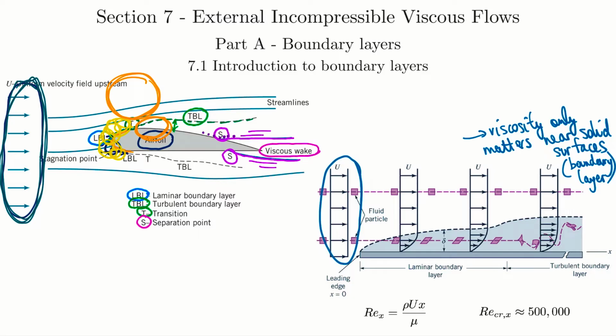Before you reach the flat plate, we have a nice even velocity profile. So out here we say U is constant, and we basically have steady, inviscid, incompressible flow. Because of those things, that means essentially P is constant as well. If velocity is not changing in those inviscid conditions, then we don't have a change in pressure either. So out there in the inviscid space, we can calculate those flows, and then we see the shaded region with the thickness denoted as this delta right here. That's what we call the boundary layer, within this dashed line.